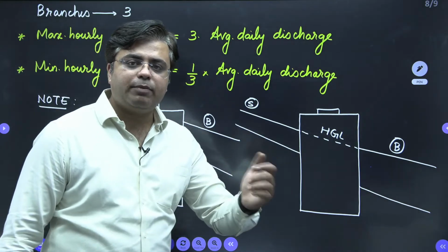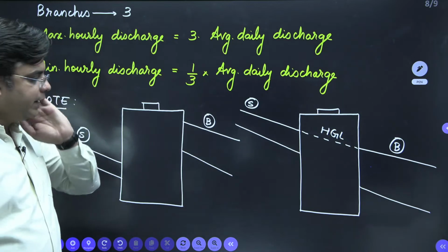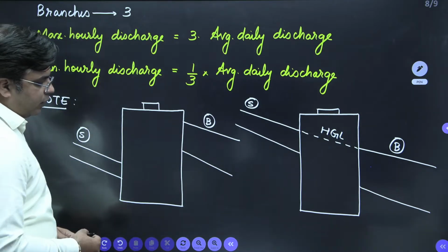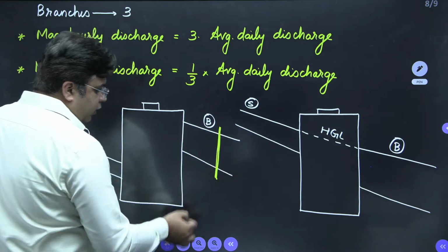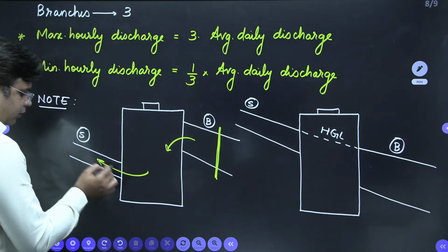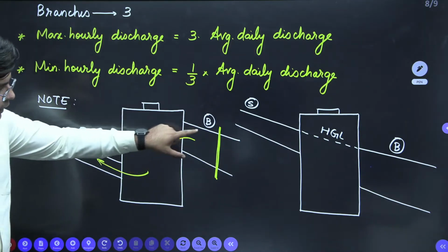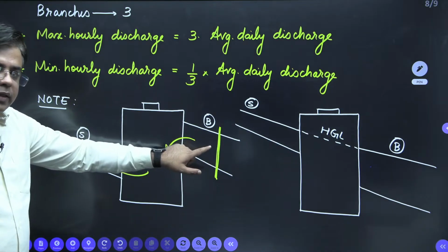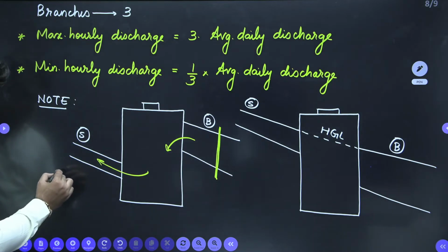Which arrangement will I practically provide while working in the field? So observe this very carefully. In arrangement 1, if any blockage happens in the bigger sewer, right? So the waste water will flow back and it will enter this small sewer. So in first situation, in case of blockage of bigger sewer, there is a possibility of backflow in the small sewer.